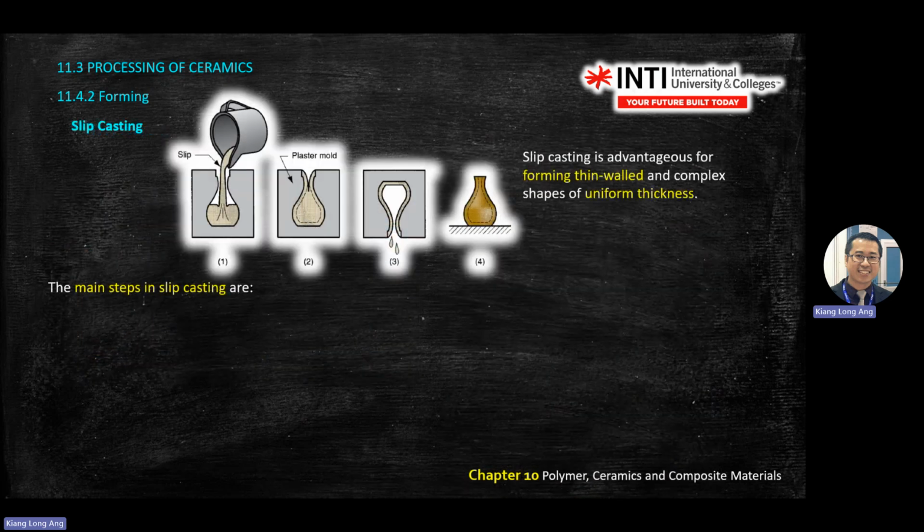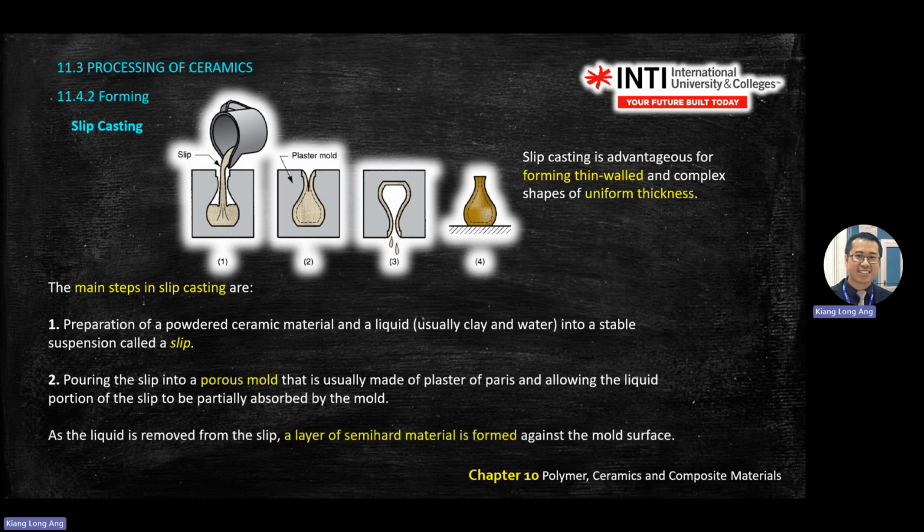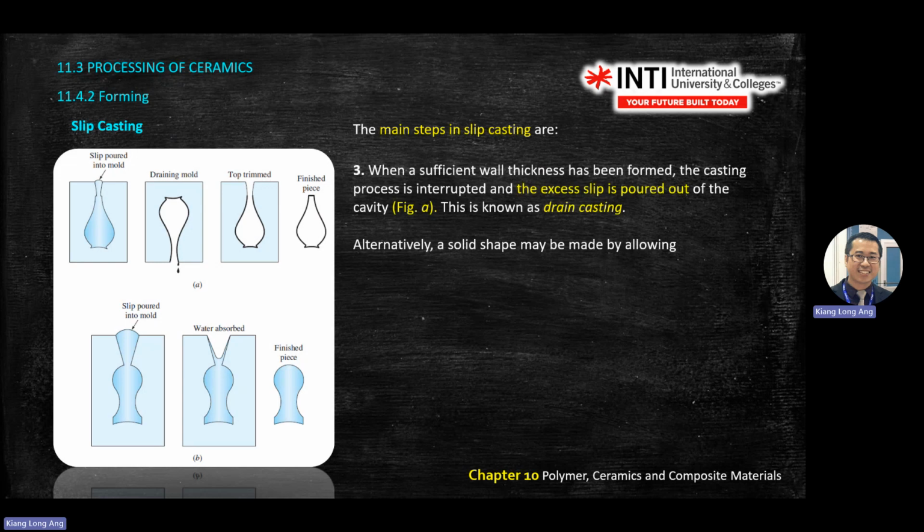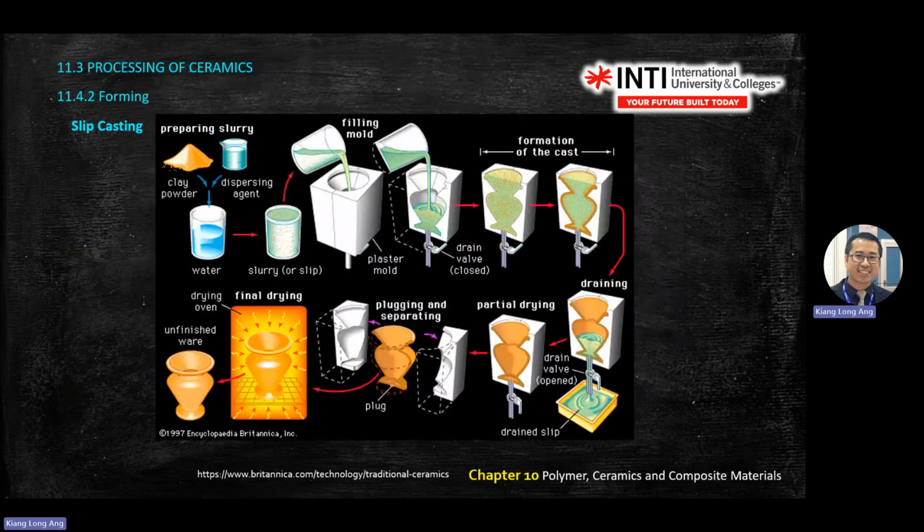Slip casting is a traditional method for vases. There is a mold, then they pour in, and then they flip the mold, dry out, they get some thickness, then they remove the die and they get a shape. This one you read, it is basically the same thing that I explained just now. This one is forming, this one is casting. You pour, let it dry, remove the sand, remove the extra cast material. Then you heat it up. Then you remove.